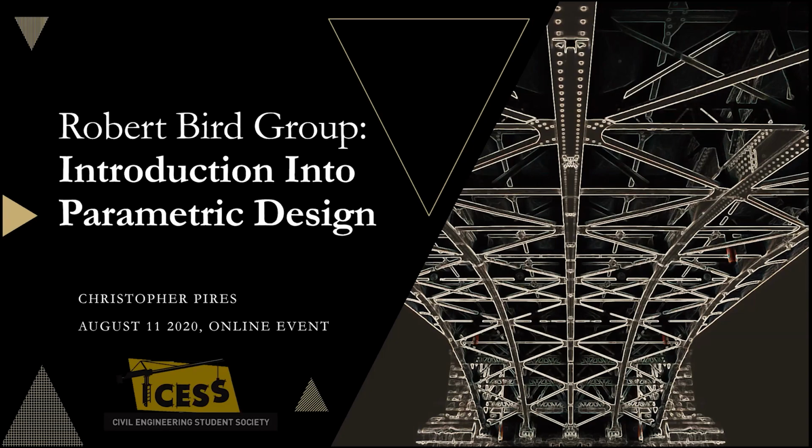Yeah. Next question. Which analytical software can be piloted via Grasshopper? Look, like Space Gass or ETABS, for example. A lot of the time you need centerline models. You can export out centerline models and also create models using Geometry Gym, which is a plugin for Grasshopper and Rhino. The other thing is, you just need to really start with learning the basics of Rhino and Grasshopper before you get into all of these plugins that I'm mentioning.